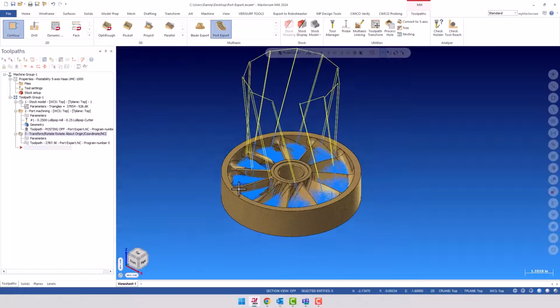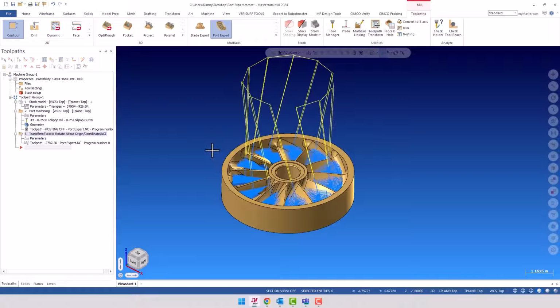The things that we can do when it's transforming is control, if we needed to, the multi-axis toolpaths. A lot of times we're doing these types of toolpaths, and this is the reason why I brought up using the transform. You may need to add an extra toolpath before and after, say, a point position of where it goes to and where it comes out. You need more of that control, and if you just do the internal transform here, you're not going to get that. So doing an external transform like I just did gives you that option.